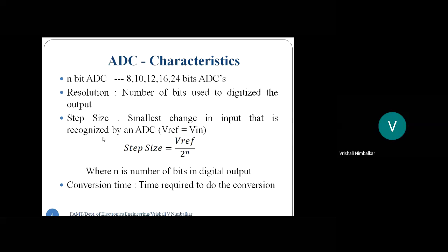Okay, so what is the step size? The smallest change in analog input that is recognized by the ADC and converted into digital is called the step size. Right. So the formula for step size is given. Step size is V reference upon 2 raised to n.